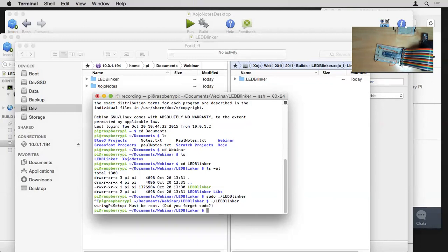But the very first time, I forgot to put in a resistor between LED and ground. And a bunch of you out there are probably laughing at me now because, yes, I melted my LED. It went up in a puff of smoke. My little office here stunk for like an hour until it got aired out. So yeah, don't do that. Make sure you know a little bit about these circuits you're trying to create before you attempt to build them and melt things.